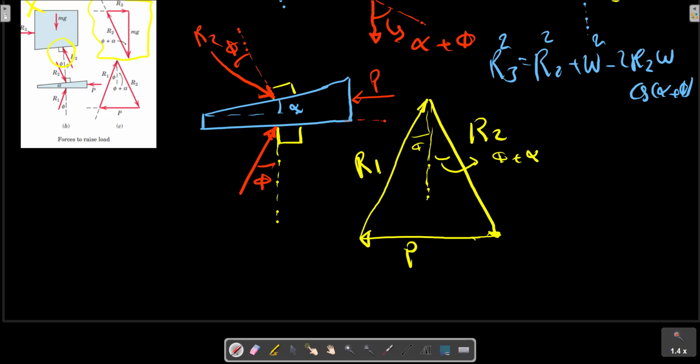We neglect the mass of the wedge. From the free body diagrams, we write the force equilibrium conditions by equating to 0 the sum of force vectors acting on each body. The solution of these equations is shown in the free body diagrams and the triangle law for the forces applied on each part.